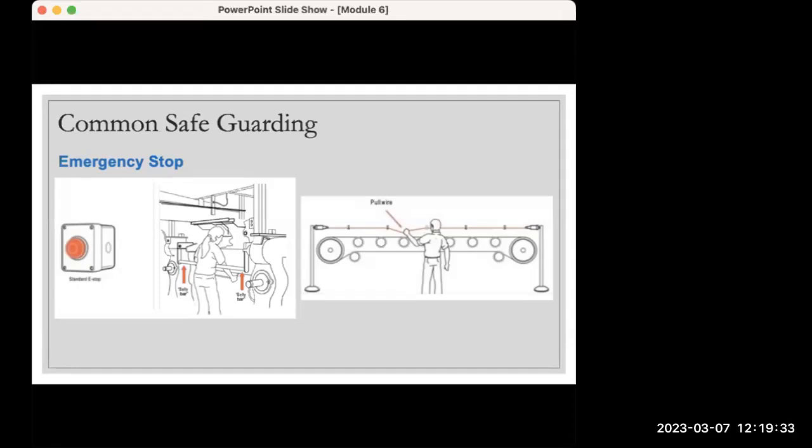You need to make sure that emergency stops are prominent and clearly and durably marked. Typically, e-stops are red with some type of yellow button. The e-stops or emergency stops must be immediately accessible to each user of the machine, have red handles, lines, bars or push buttons, and labelling can also be used, and are not affected by electrical or electronic circuit failure.